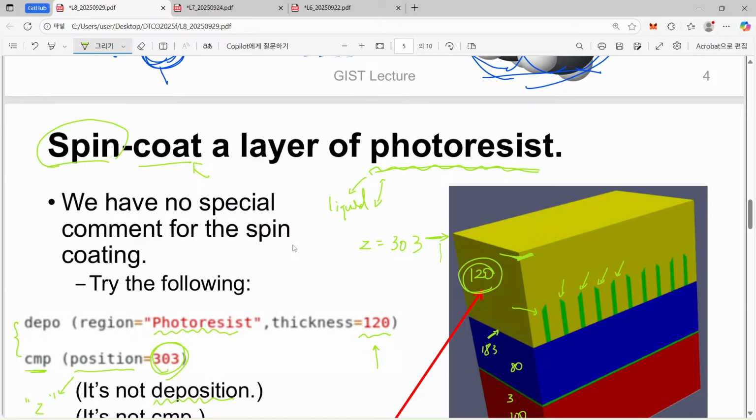Then who decides this thickness? Of course, the amount you first give onto the wafer determines the total amount of photoresist, but at the same time the speed is important. If you spin quite fast, there is a tendency that your thickness is reduced. You give something and just rotate it, and some of it will escape from the wafer top surface, and the remaining is quite flat.